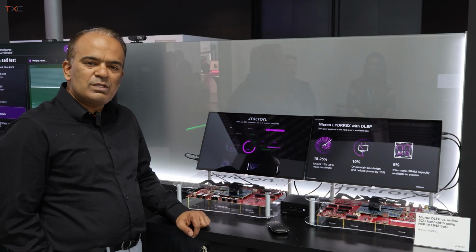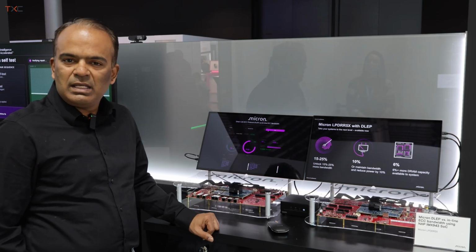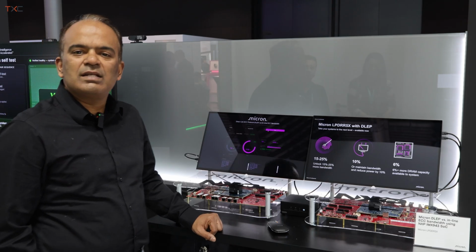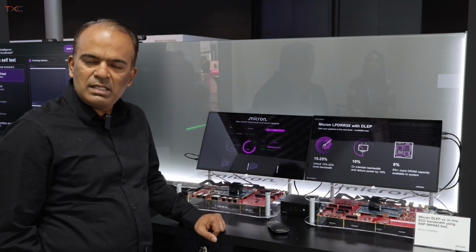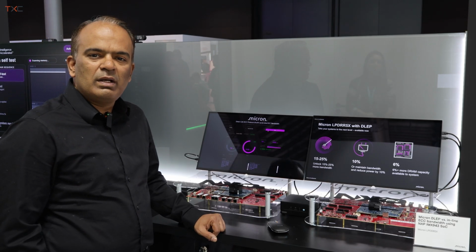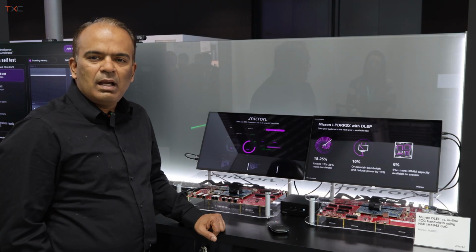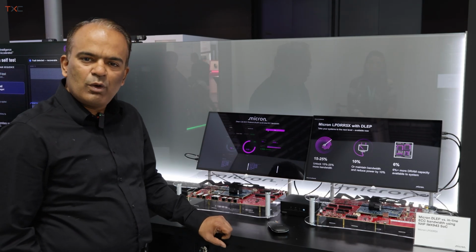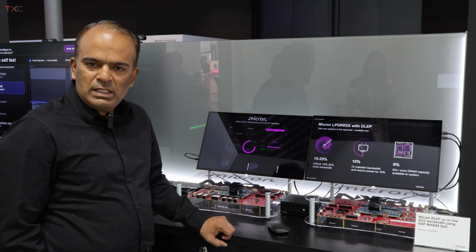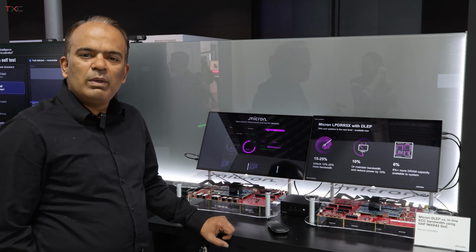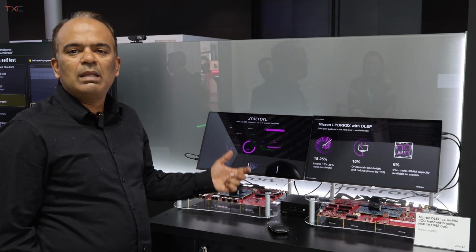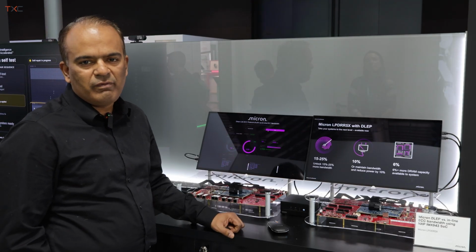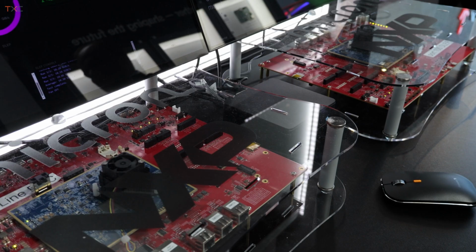What it does is, we have ECC redundancy in our DRAMs. And then on top of that, system designers always have their own system ECC. And just to make sure we're being efficient, we have worked and partnered and collaborated with our system OEMs and SoCs and figured out a way where we can give some of that capacity back to the system, so it eventually allows for a higher bandwidth and a higher performance.